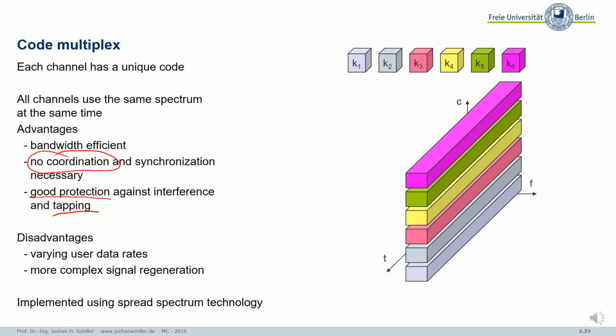What does it mean? What is spread spectrum and why do we use it? So for now, basically, we looked at channels, what we call narrowband channels. These are all channels on certain frequencies. And there we modulate our data on the channels. Okay, so modulation technologies, and then we have channels. But there's also a technology that says, no, I don't want to use a narrow channel, but I use a very wide channel. Why this?